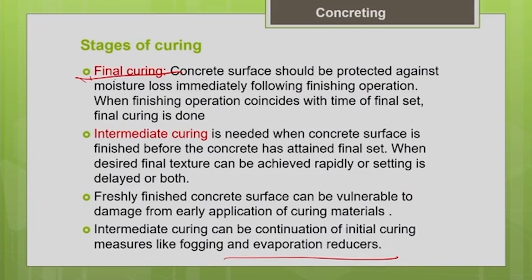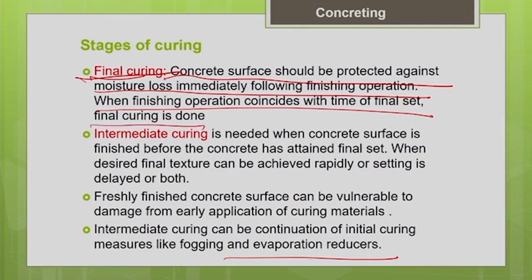So, what is this final curing? The concrete surface should be protected against moisture loss immediately following the finishing operation. That is the traditional way. Once the finishing is done, immediately we have to do the final curing to prevent moisture loss. Mostly the finishing operation coincides with the time of the final set, so it will be convenient to do the final curing. There you can apply your water and do the final curing.